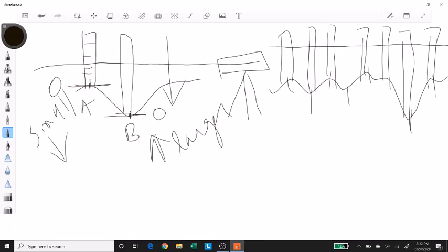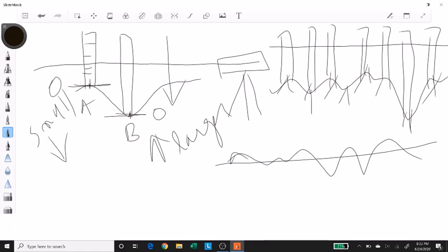So once you have all of these values, what you can do is you can draw the profile of the land, and not just the profile. You can use it to find out water carrying capacity of a valley. You can find out a number of things. Let's say you want to build a road in a terrain that looks like this, and if you have this profile of the land, you can decide on the grade of the road and the elevation of the road, because you have different options.